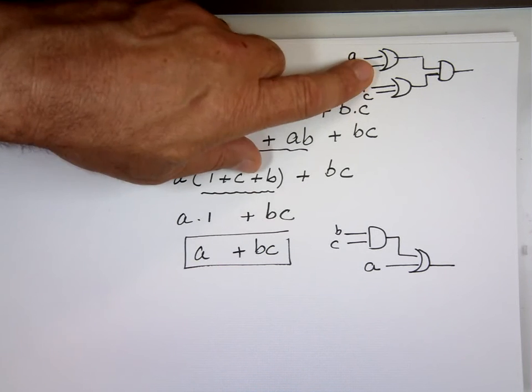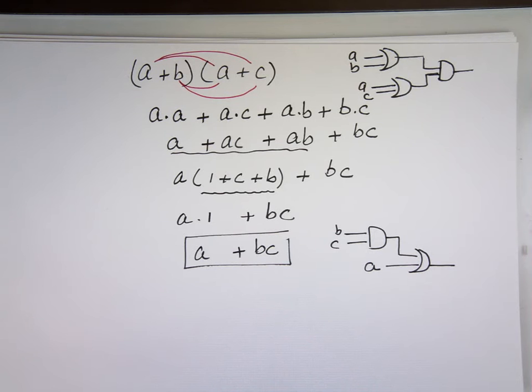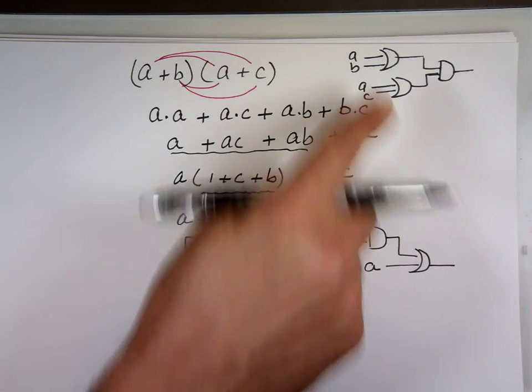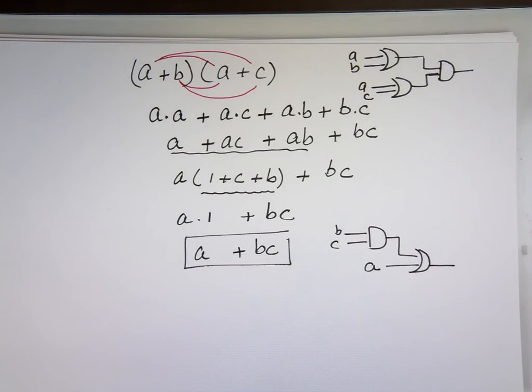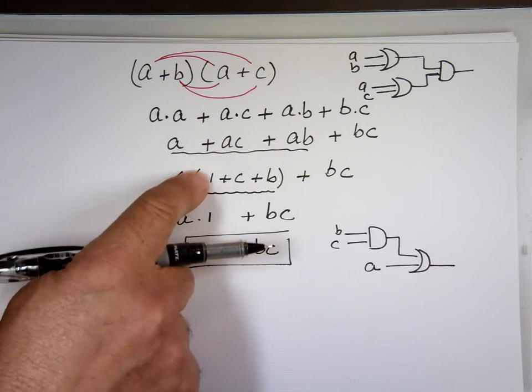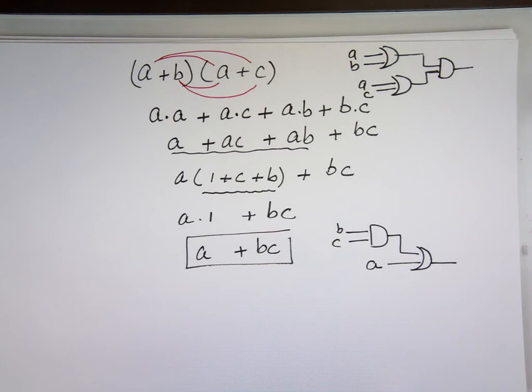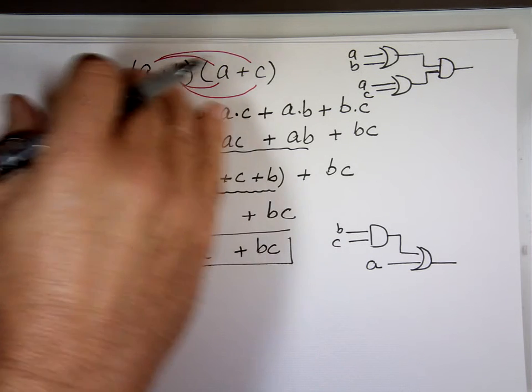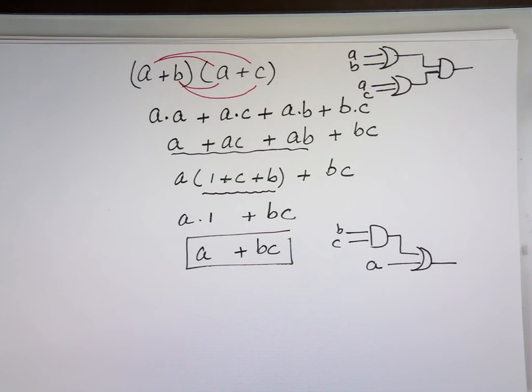Well, when you buy a chip, it has 4 of them. So if you need 1, 2, 3, or 4, it doesn't make a difference. The same chip. But when you're building a big circuit, you save an OR gate here, you save an OR gate here, an OR gate there. There goes a chip off the board. So you're going to see us actually go through the Boolean algebra, try to take some ugly expression, a bigger one, simplify it so the design is smaller. That's what we're trying to do with the Boolean algebra. Simplify that expression.